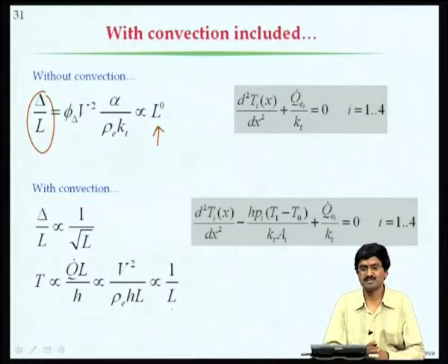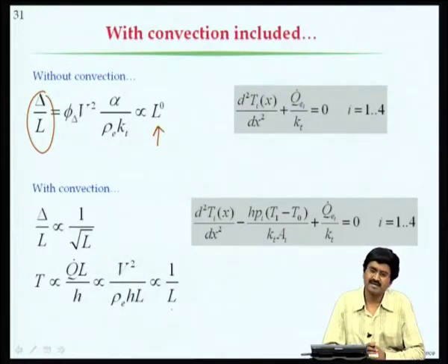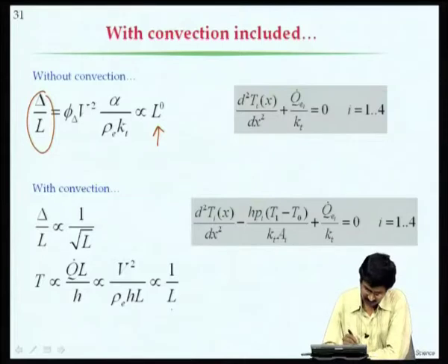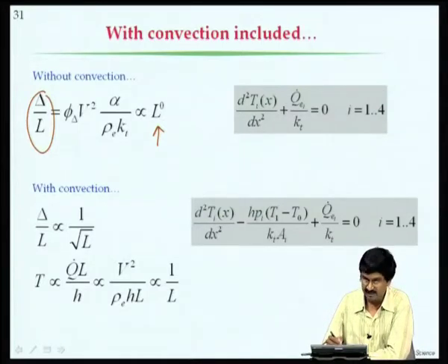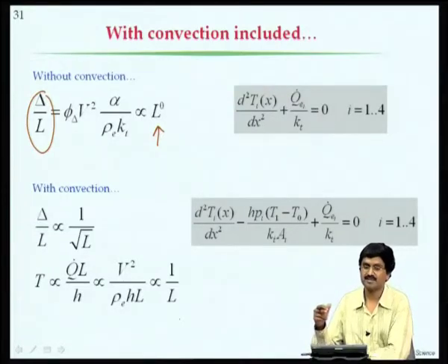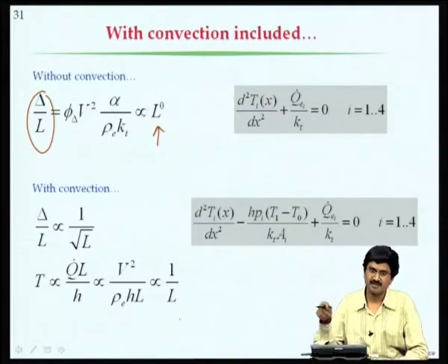So, electrothermal actuation actually works more at small sizes, micro or 10 times larger, but not at macro scale. Although thermal loading is huge in terms of leading to cracks in buildings and making bridges collapse, when you actually want to make an actuator, its temperature difference is going to be inversely proportional to size. Accordingly, the deformation, everything will also be more at the micro scale, but again it depends on the properties, electrical resistivity, thermal expansion coefficient.